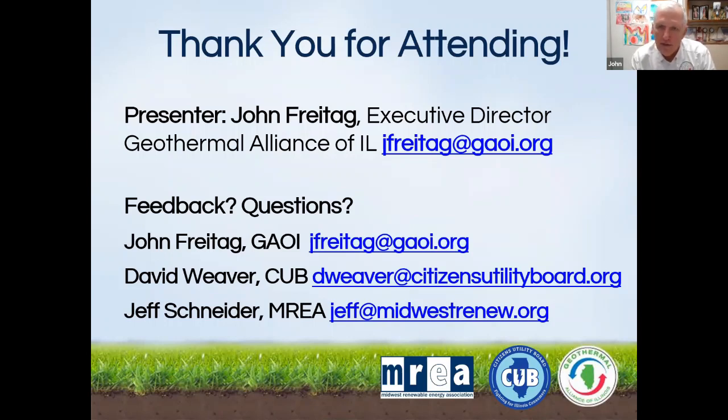If you're connecting a geo system to a water heater, the last thing you want to use is a so-called cheap water heater that's going to rust out and spring a leak in 5 or 6 years. And then you've got to go through the whole rigmarole of replacing that water heater with the desuperheater attached to it. It's just better to spend a little more money and do it the right way and put in a Marathon water heater or one that's similar, like the one I have about 5 feet from me.